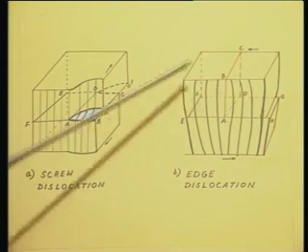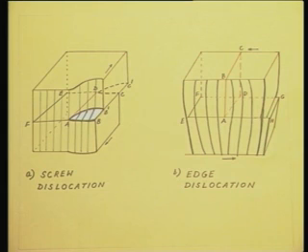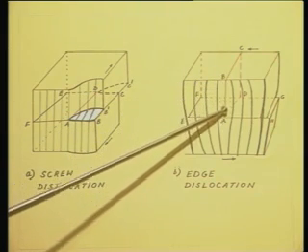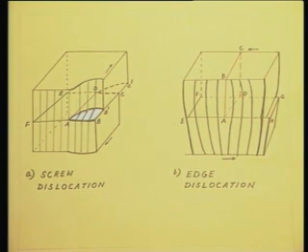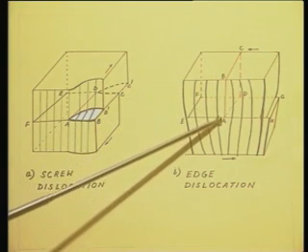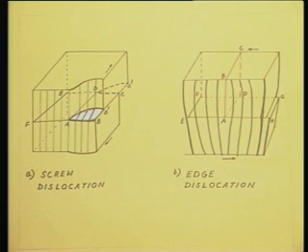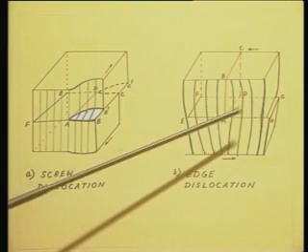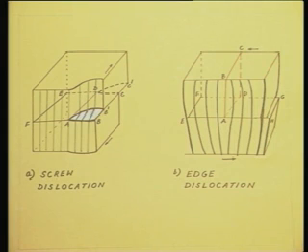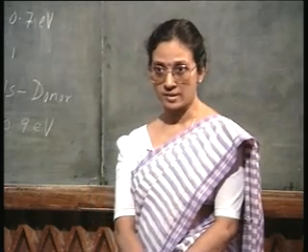See, if you view it in 2 dimensions, then all these black and red lines actually signify the array of atoms. Atoms are placed along this array. So, what you have done is you have created an extra half plane, it is not continued throughout the crystal. Only in the top half you have created an extra half plane of atoms. This is called an edge dislocation, extra edge. This is because the top half of the crystal has got displaced by half an atomic spacing. You can see it here, it has got shifted by half an atomic spacing and it has given rise to one extra half plane of atoms. This is an edge dislocation. So, you can have either a screw dislocation or an edge dislocation depending on the type of stress it is subjected to.